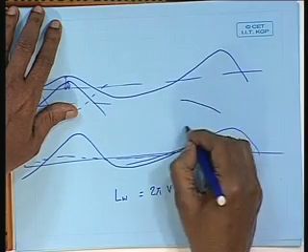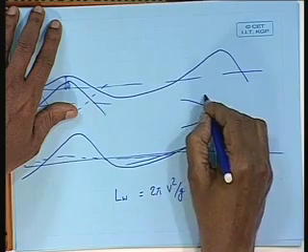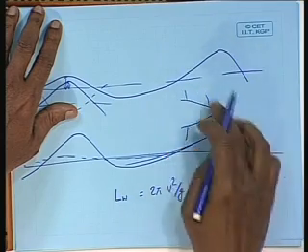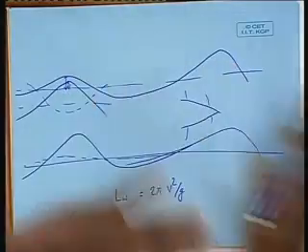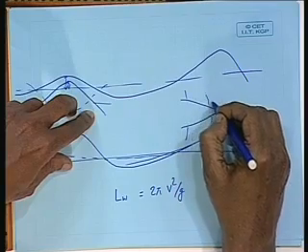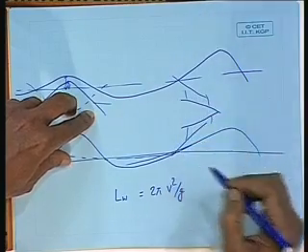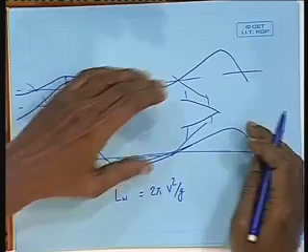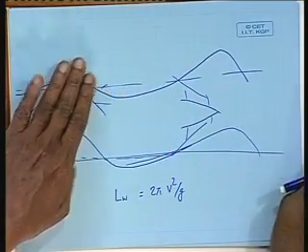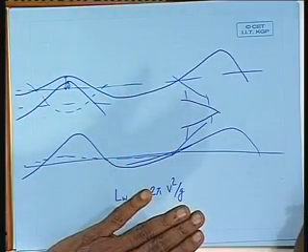Imagine this is my ship, and these are the transverse waves. These waves will move at the same speed as the ship. Now, let us take the divergent waves. How will these move? The axial component of velocity will be the same as that of the ship. Otherwise, they can't keep on getting generated, and you will not see the waves moving along with the ship, isn't it? So, the axial component will be equal to the speed of the ship.